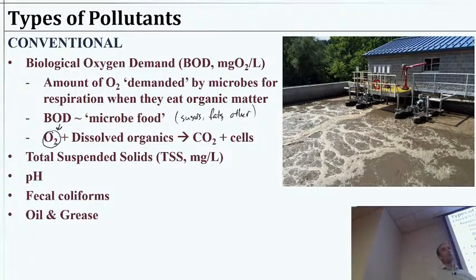Now, if you go to a wastewater treatment plant that's operating well and it has a nice aerated system, you would expect it to smell terrible because it's wastewater. Actually, if it is operating well and everything is aerobic, it just smells like slightly stinky dirt. It doesn't smell too bad. When you have anaerobic processes, which sometimes is on purpose, that's when you get the really bad smelling stuff. So this will also improve the smell, which is kind of our body's indicator. Is something rotting? Is something fermenting? Is something bad here? If we give it plenty of oxygen, we'll notice that too.